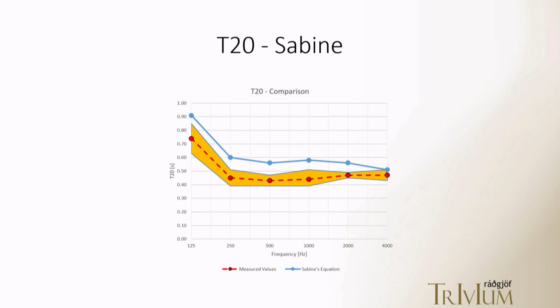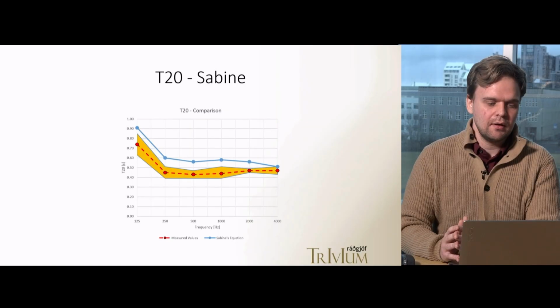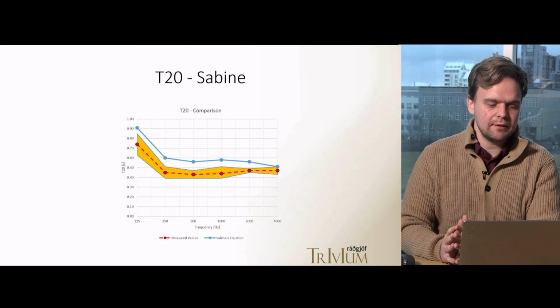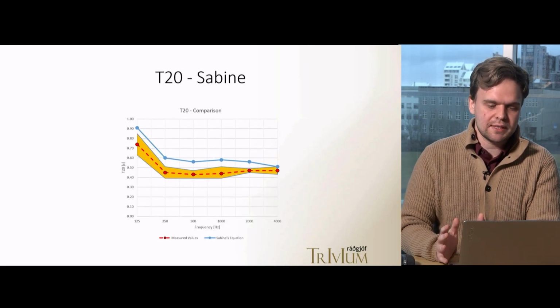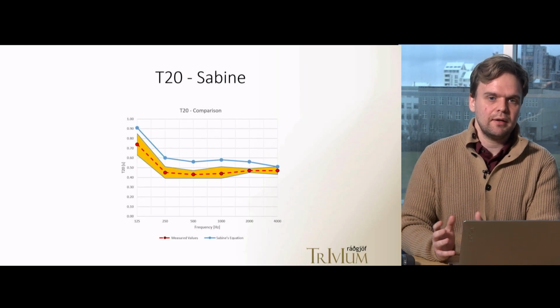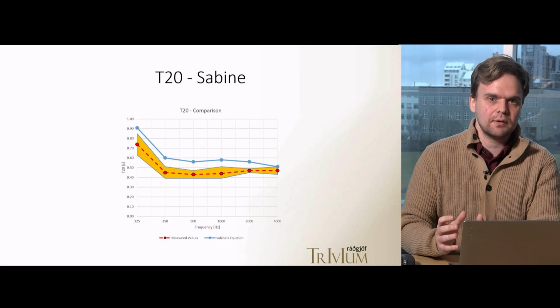Even so, as far as using Sabine in small rooms goes, with its inherent problems and non-diffuse sound fields, this room is probably as good as it gets. The reason I say that is that the acoustical treatment does not cover the whole ceiling, so we don't have an extremely dominant sound field in the horizontal directions compared to the vertical ones.